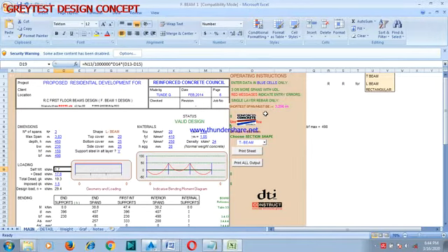Shortest span must be. Now because our maximum span is 3.83, it's telling us here that in this beam the shortest span must be greater than 3.256. Now if it is less than, I don't want to go deep into explaining these.